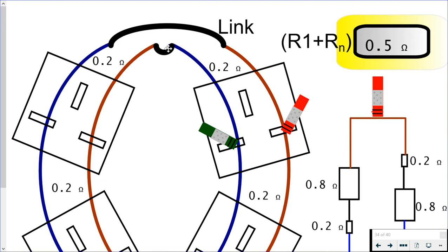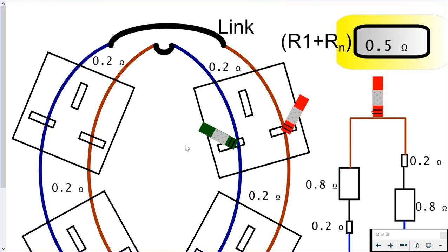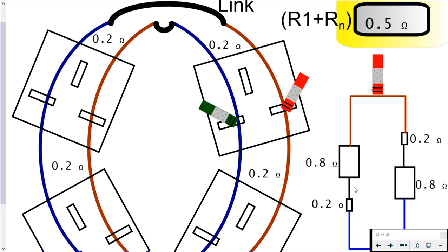Well, when we interconnect our ring final socket circuit at the board for stage 2, we connect our incoming neutral to our outgoing line, and we connect our incoming line to our outgoing neutral. Okay. If I was to grab these ends of the cables down here and open them up, I would get a figure of 8 on my loops. Okay, so you see the wee black links here. There's the representation of our black links here.